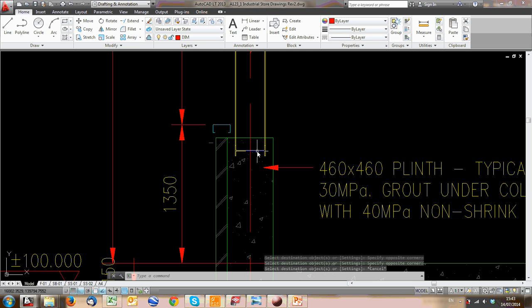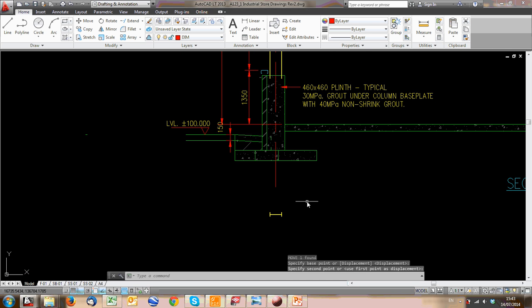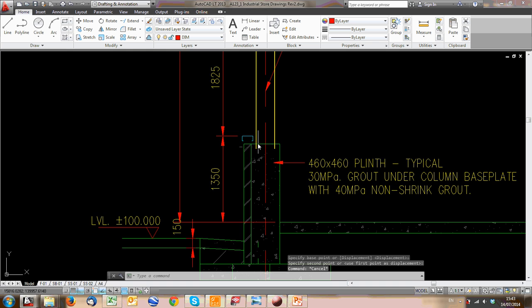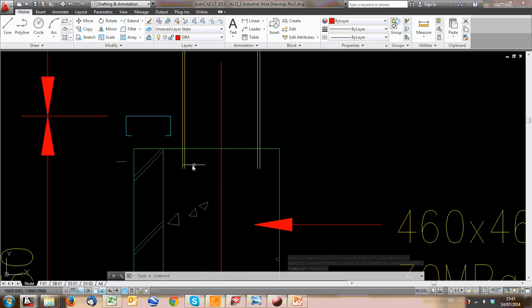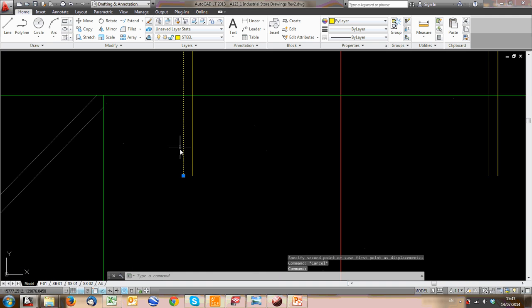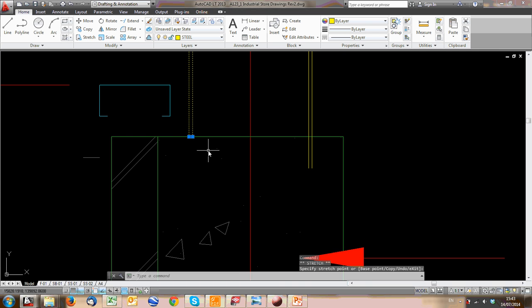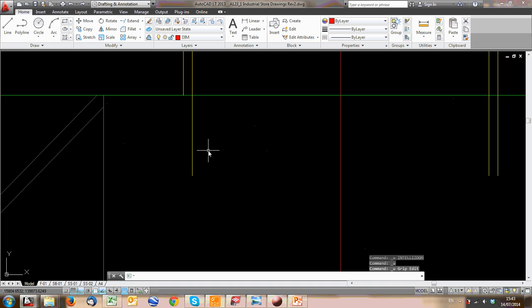But now the column, I can move him out of the way. Just get him out. The column extends too far. Let's say I want to trim him off at that level. Either you can go and manually adjust, so you click on the line and you click on the point, and you can go and manually adjust all of those. Otherwise, there's a faster tool called trim.